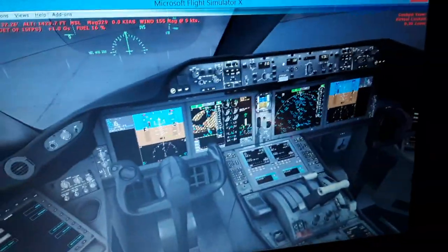If we set a higher altitude, you will see the terrain also. When you fly and you have some mountains, you're going to see them. So in the navigation display, also the outside the aircraft system, you can see the terrain and weather effects from the weather radar. You can see the terrain with the red, green, and yellow indications, with blue the lakes, the rivers, the sea. Also in a horizontal and vertical profile, you can fly the aircraft close to terrain and you see the terrain below you or in front of you. Depending on the distance, it will change color, like yellow, green, or red.